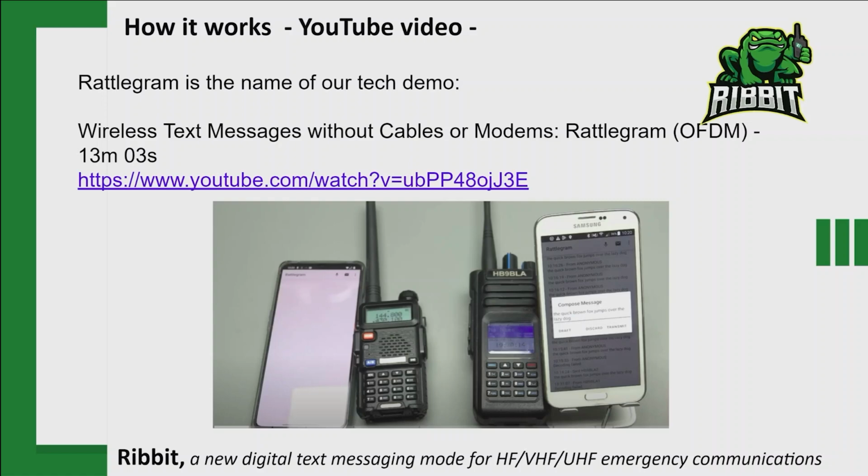So you're using acoustic coupling between the HT and the phone. If you had a cable, could you use the cable and increase the performance, the throughput, and not have to listen to it all? The easiest quality of life improvement you can have is an APRS cable. If your phone has a 3.5 millimeter jack and you've got the Kenwood connector, that would work just fine, and you would reduce ambient noise, so you would increase your transmission success rate.